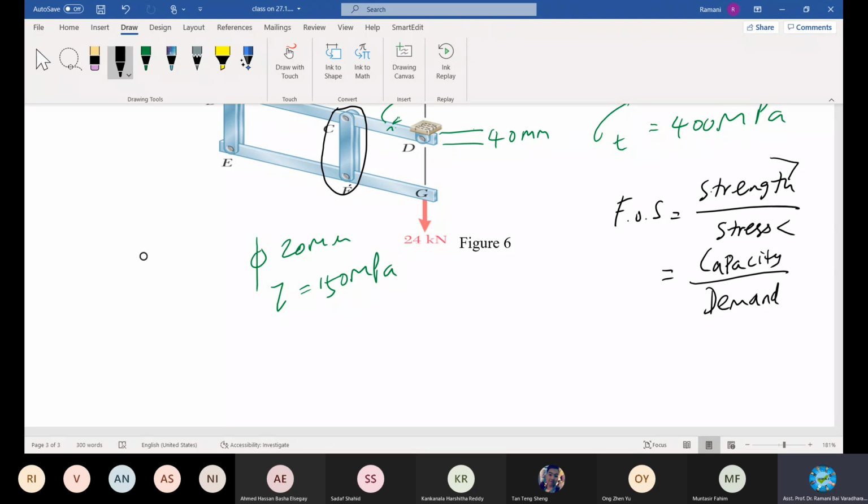Yeah. That's why factor of safety is always greater than 1, because of this equation. If you have a higher capacity and the demand is so and so, you are still accommodating, isn't it? That is why you need to have this factor of safety always higher than 1, which is the normal case. I already told you in RCC design we use 1.5. In these trusses, they may go to 2.5, even 4 also they can keep. Okay, these are all the theory about factor of safety.